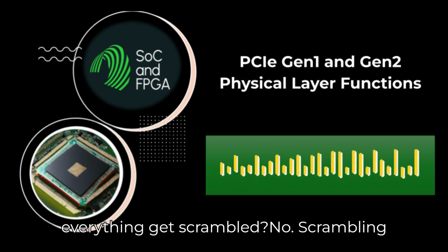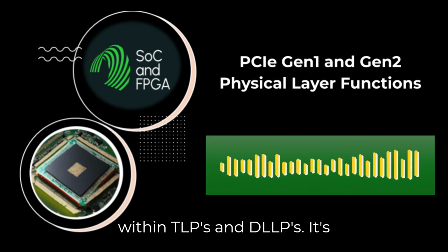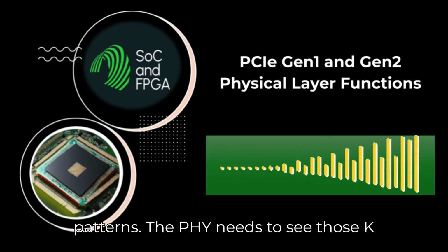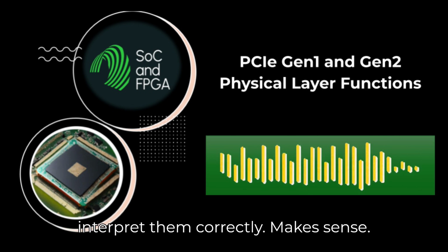Does everything get scrambled? No. Scrambling is only applied to data symbols, D-codes, within TLPs and DLLPs. It's disabled for all special symbols, K-codes, all ordered sets, and certain test patterns. The PHY needs to see those K symbols and ordered sets unscrambled to interpret them correctly.